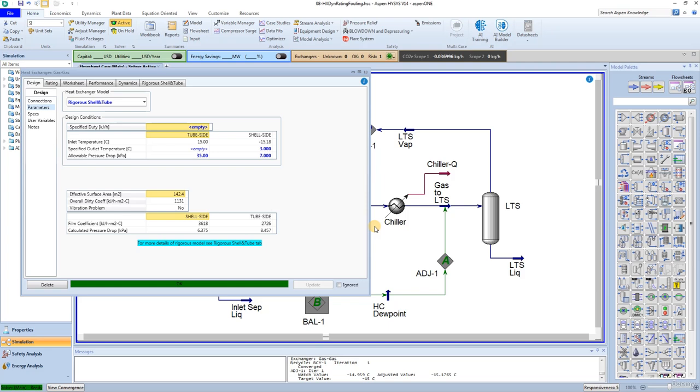When this model is selected, HYSYS takes the known process inlet conditions for the exchanger and sends them into the EDR calculation engine. EDR then computes new outlet stream conditions based on the selected geometry. As a result of this calculation approach, we cannot have any of our former HYSYS simple weighted model input values present.